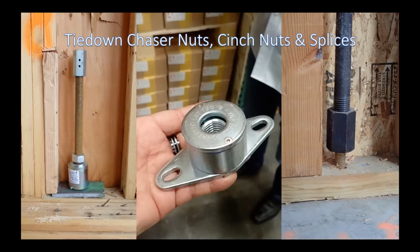So it's continuously self-tightening. The one in the middle, the cinch nut, is also self-tightening, except that one you don't have to initiate. The minute it's used, it has a continuous action, with no limit as to how far the ratchet action will go. So yeah, those are some of the different systems being used over here. And these are also readily available. There's a big project with this in Mary Potter, I think, in Wellington in New Zealand, taking place right now.